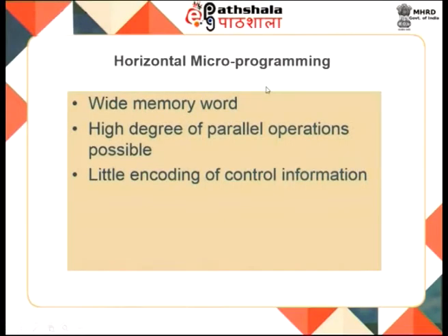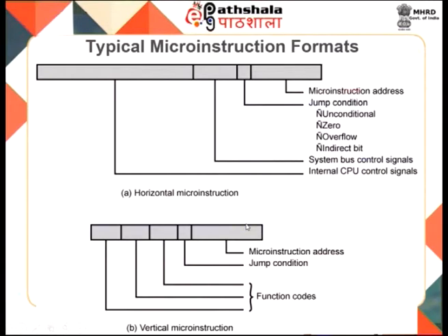On the other hand, if you look at horizontal microprogramming, it has a wide memory word, there is a high degree of parallel operations possible, and there is only very little encoding of control information. This gives you an idea of these two formats.